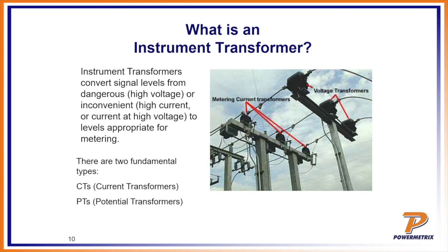If you look at the picture here, you can see the CTs and PTs are actually mounted on two different bases. For an industrial commercial site, typically they're mounted in the same place. If it's a pad mount, you'll see PTs and CTs mounted into the same pad, and a lot of times nowadays you don't see PTs at all, which is kind of the reason I'm not talking too much about PTs. They're mostly used in a primary or substation application.